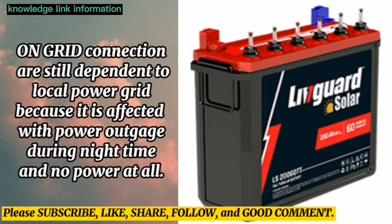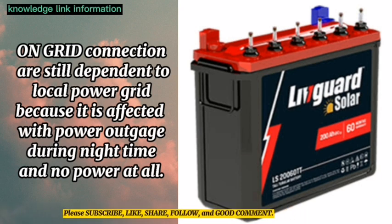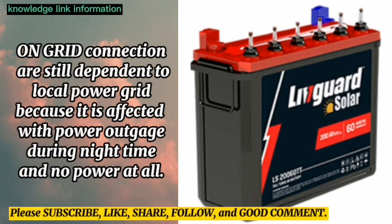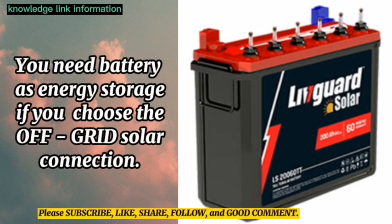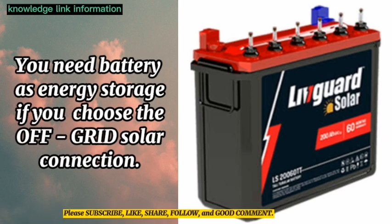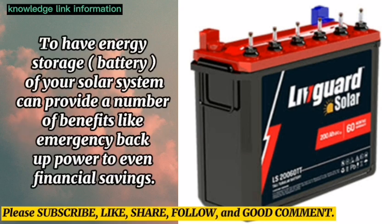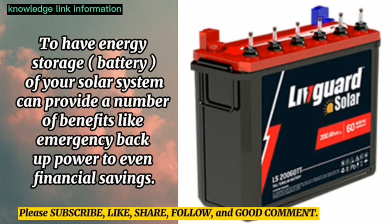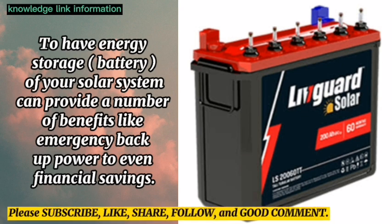On-grid connection is still dependent on the local power grid because it is affected by power outage during nighttime, with no power at all. You need a battery as energy storage if you choose the off-grid solar connection. Having an energy storage battery in your solar system can provide a number of benefits, like emergency backup power and even financial saving.